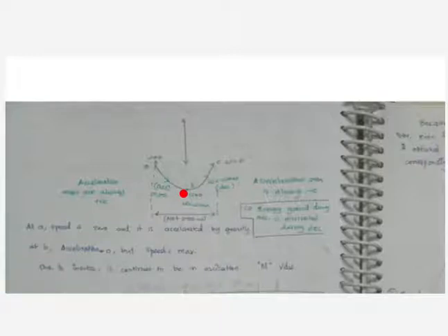Then it starts swinging and it will go to the point where omega is equal to 0, right? And it swings back to the point where again it becomes 0 and it comes back. It starts from here, it goes, it comes back, it goes, it comes back, and it finally settles, right? What it's saying is that the area between this original point and the maximum acceleration point, and the area from omega 0, this net area will be 0. This area will be equal to this area.